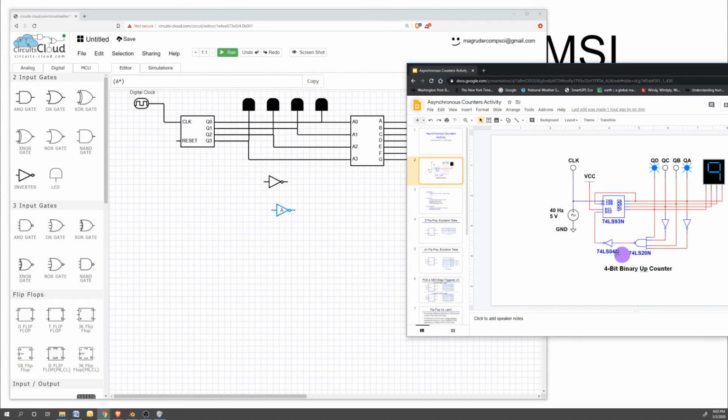We are not yet taking advantage of the reset functionality on this counter. And so the last bit here is to rebuild this control structure logic. What we want to notice is the intended behavior: we're enabling this reset at a very specific point. We want this counter to show 9 for a full clock cycle, but we don't want to show the next value, whether that's A or 10. We want to specifically reset after 9 and before 10. So the way we do that is as soon as our outputs read what would otherwise be displayed as A, right?